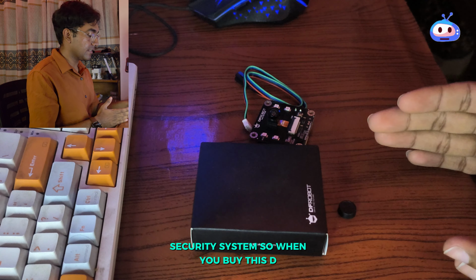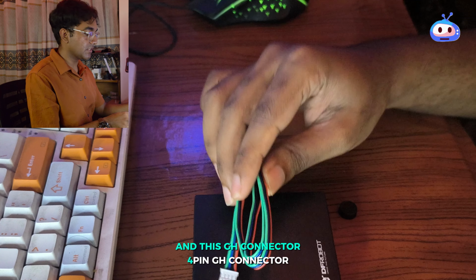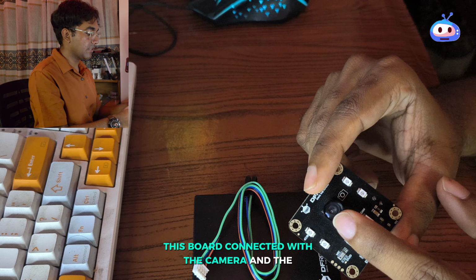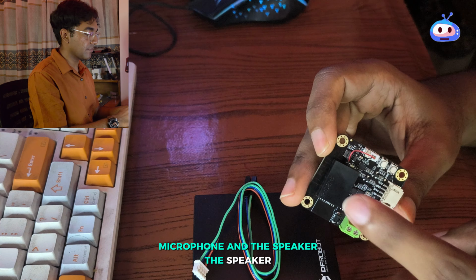When you buy this DFRobot ESP32-S3 AI camera, you'll find this box and a 4-pin GH connector. The board is connected with the camera, and the microphone and speaker connect at the back. The camera is a 160-degree wide-angle, 3 megapixel OV3660. This is the ambient light sensor, and this is the LED, and there are 4 IR sensors. In the back you will find the speaker connector, power connector lines, the USB connector, 4-pin GH connectors, a boot button and a reset button, and obviously the processor of this ESP32.